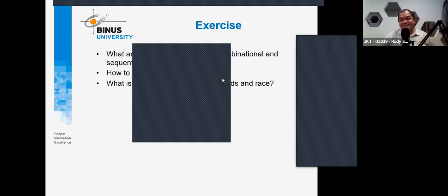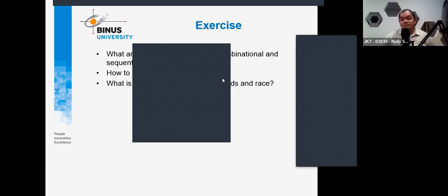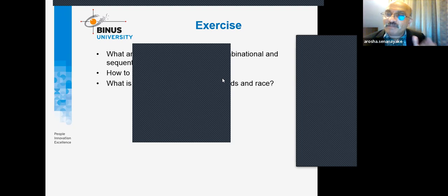But a shift register alone is not sufficient. If you have a shift register, you anyway have a clock there, no doubt. The only thing is that there should be a buffer between the shift register and the processor, because from the keyboard the key press goes in serial,